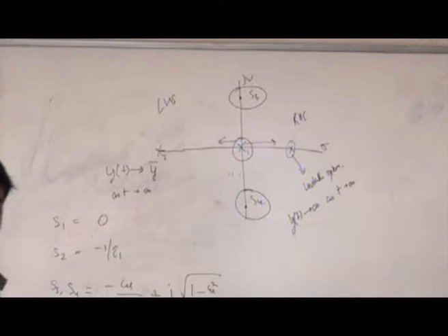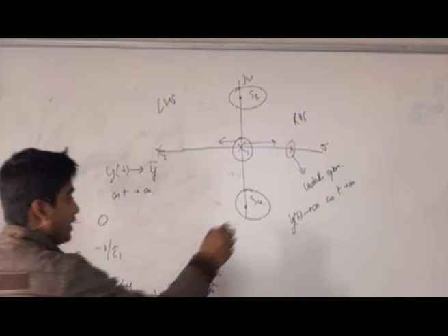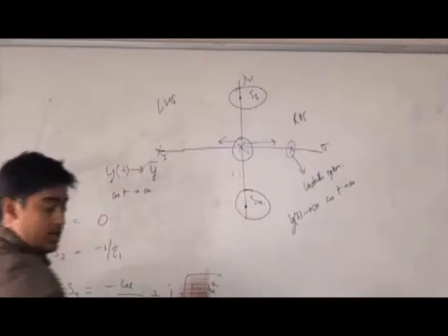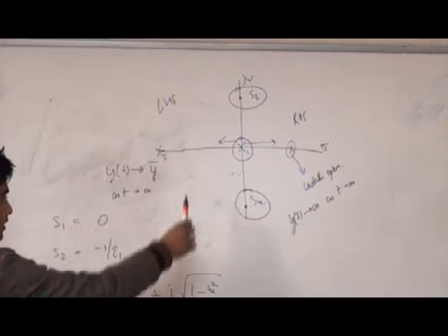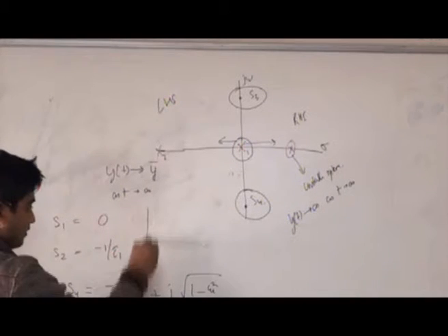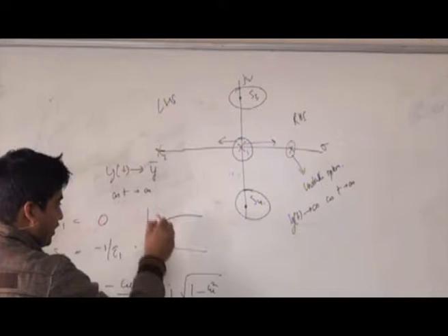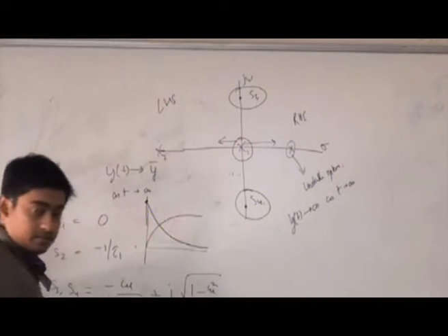For these poles which are just on the imaginary axis, first of all, they occur only in complex pairs. And when these poles are on the imaginary axis, you will see an oscillatory behavior. A pole on the real axis will show you the exponential behavior, having an initial condition at this point, it will go like this.